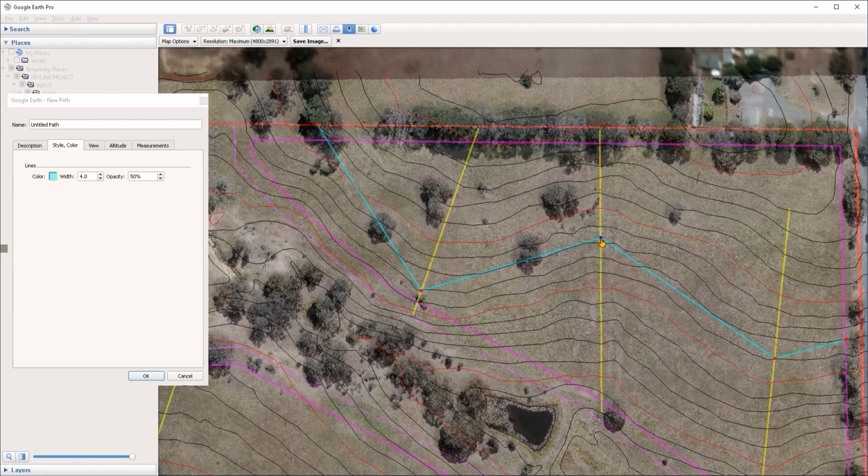For example, if I put the guideline right here, it's not necessarily going to be perfect when I start offsetting it up and down the slope. There may be some areas where the geometry is not flowing from valley to ridge, and that's okay if it occurs just occasionally. What you're looking for generally is a pattern that is, let's say, 70 to 80% technically accurate, and for the remainder you can make compromises if that means you can keep the pattern simple.